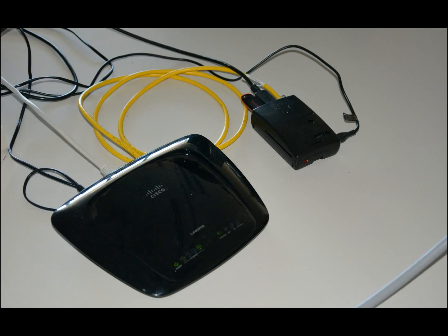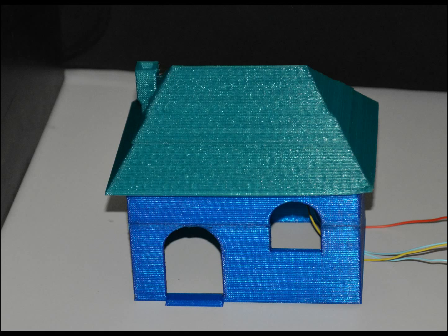The user can send a set point for the light intensity value, but can also choose the user mode, auto or manual. When the auto mode is selected, the Arduino will regulate the light intensity to reach the set point, but the light can be switched on only if somebody is in the room. Indeed, a detection sensor is installed into the room.